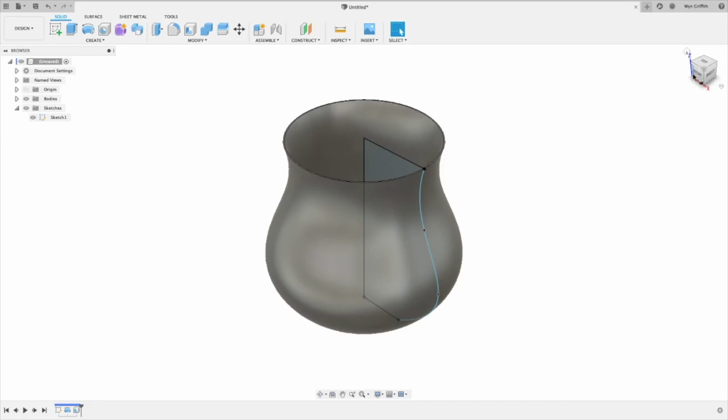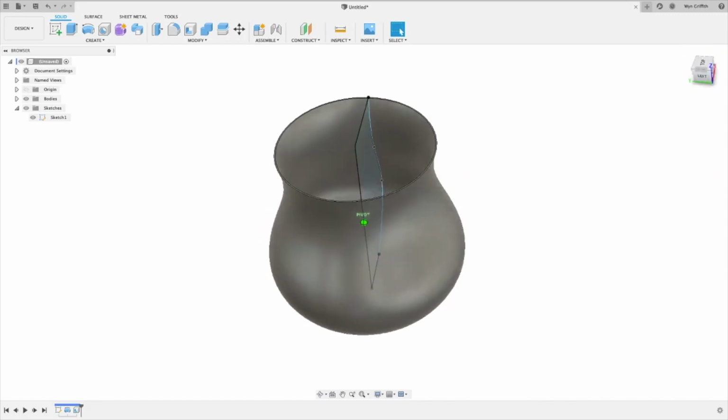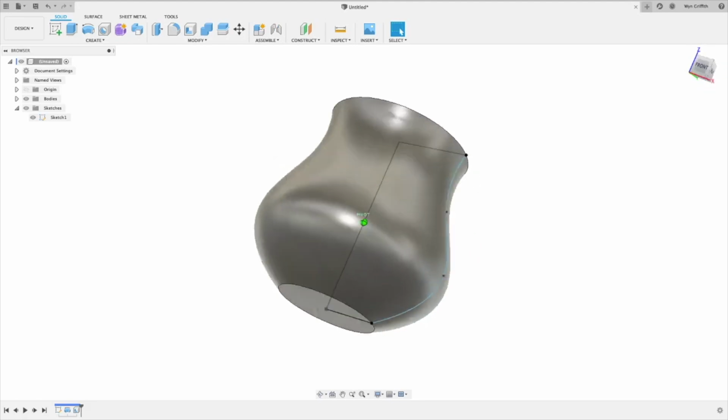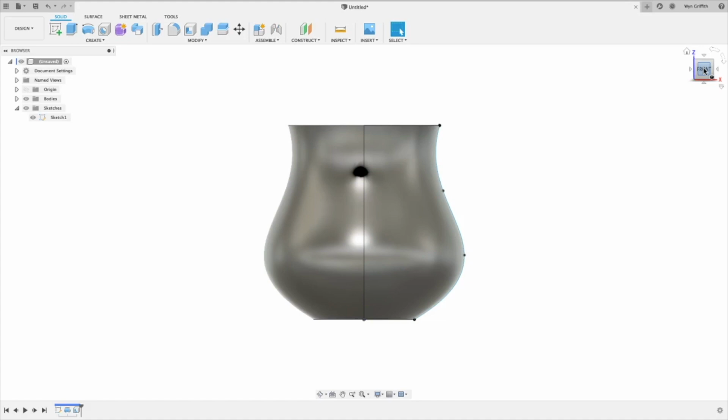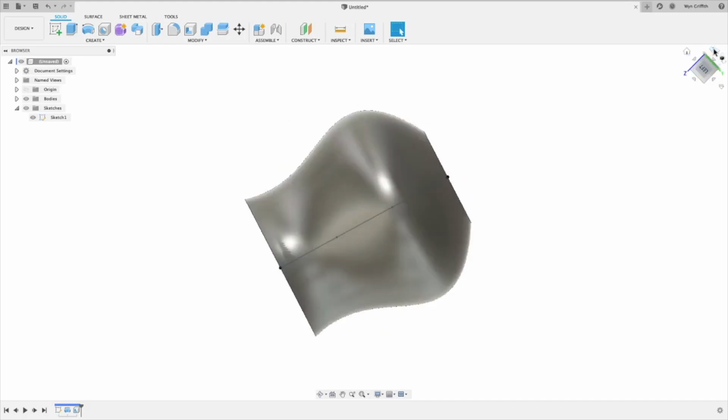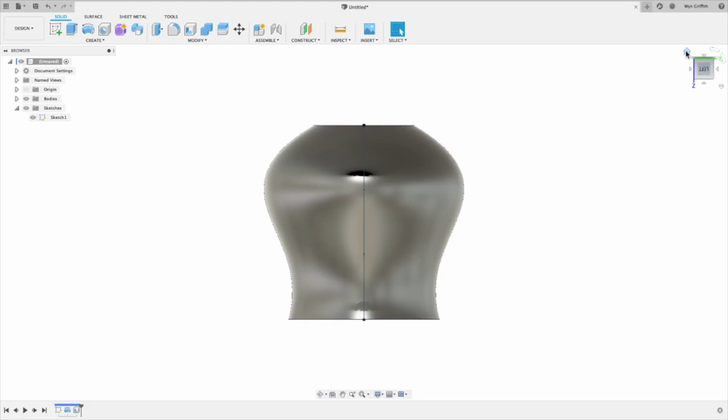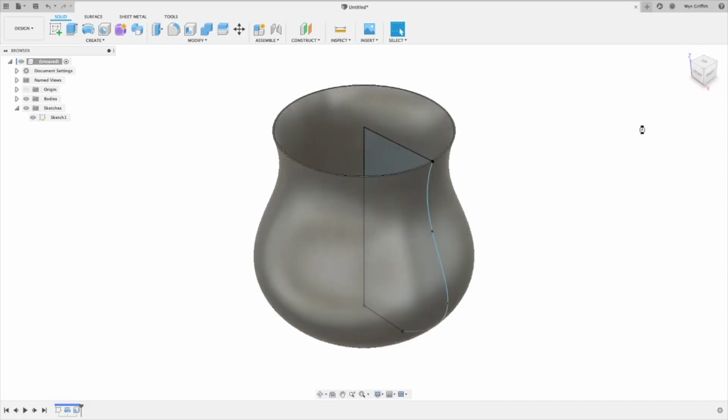Okay. This cube as well, you can actually left click on the cube, you can drag the cube and that'll help you to rotate your model. You can actually click on the faces of the cube and it will turn to face that face. Okay, or if I wanted to go 90 degrees to the left here, I could click this little arrow and it would do that. I could actually rotate it about that axis as well if I wanted to. But if I hit the home icon, it'll always go back to that position.